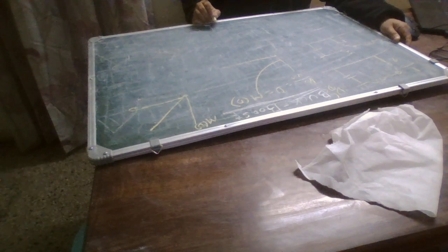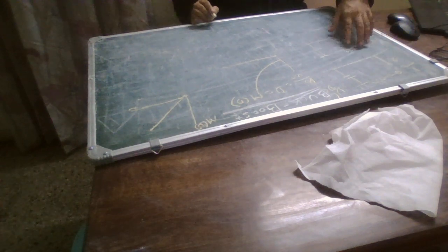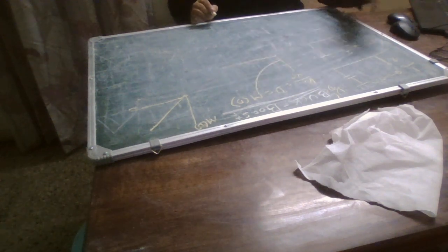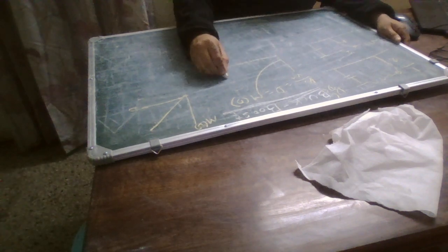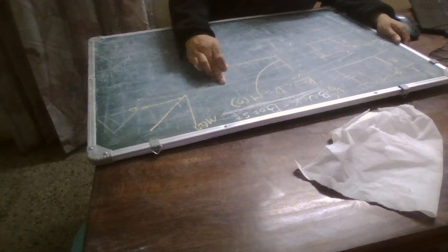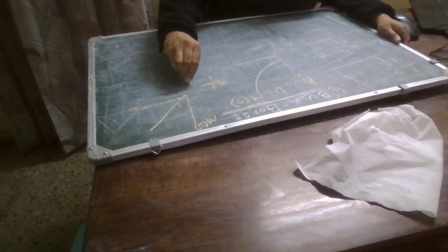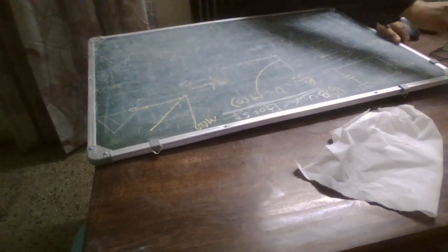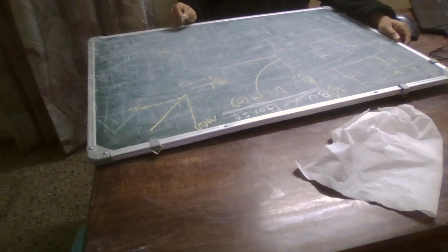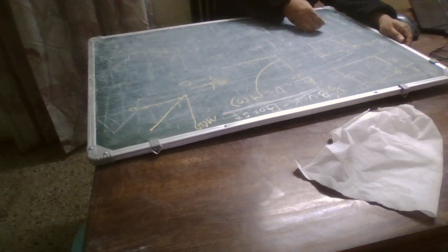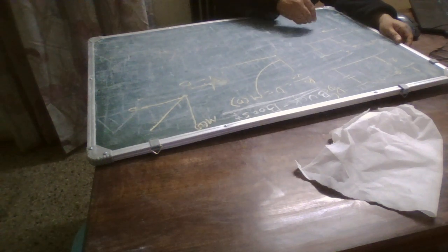Now I would be cascading both these converters, buck along with the boost. Here the conversion ratio was 1 upon 1 minus D. We will soon see that if I am going to drive a buck boost configuration, that would have a polarity of minus, known as an inverting buck boost converter.